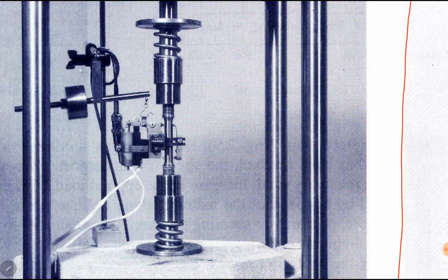And we have to find internal forces in these 3 sections. Because area is known, it is external. Length of each section is known, it is external. E is known for each section, but load P is internal. So we have to find internal loads in each section.